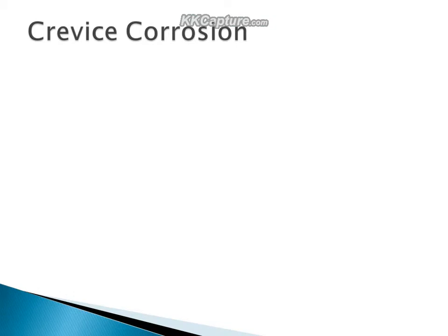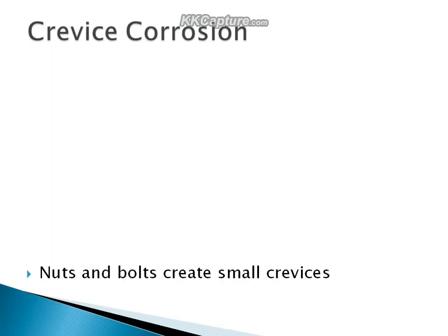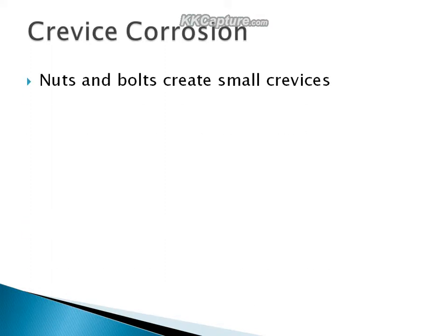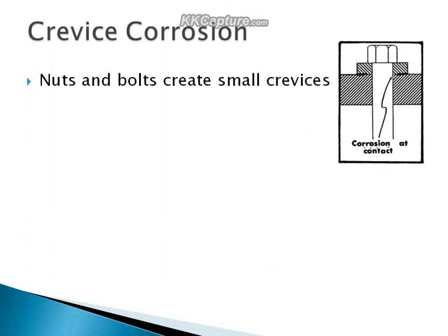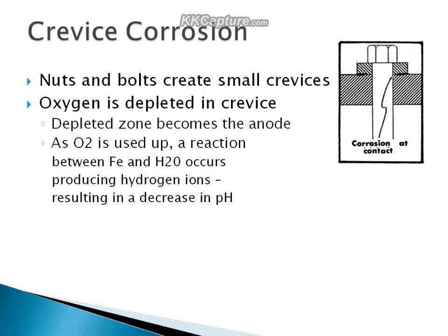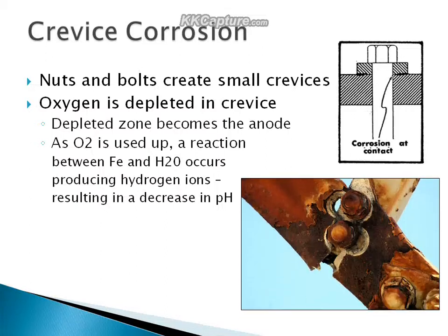Crevice corrosion is another form of corrosion whereby a small region adjacent to the nuts or bolts becomes depleted of oxygen, causing a reaction between the iron in the steel and the hydrogen ions from the moisture or water. This creates a drastic drop in pH level, which causes an acidic region and accelerated corrosion rates locally. This emphasizes the importance of eliminating crevices and humidity on the structure.